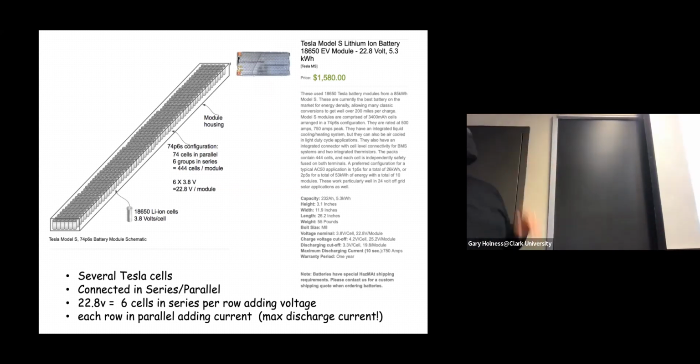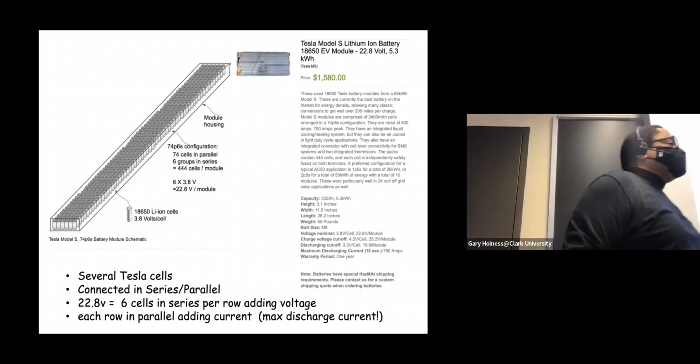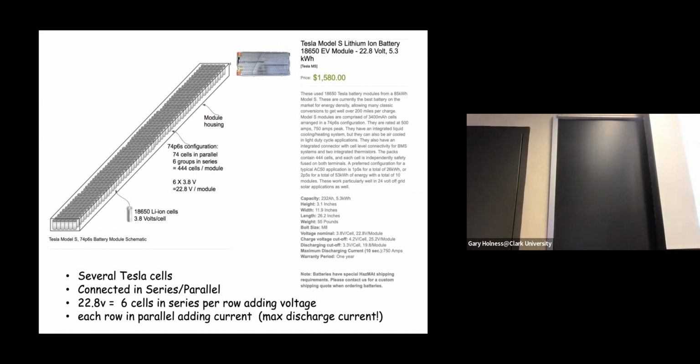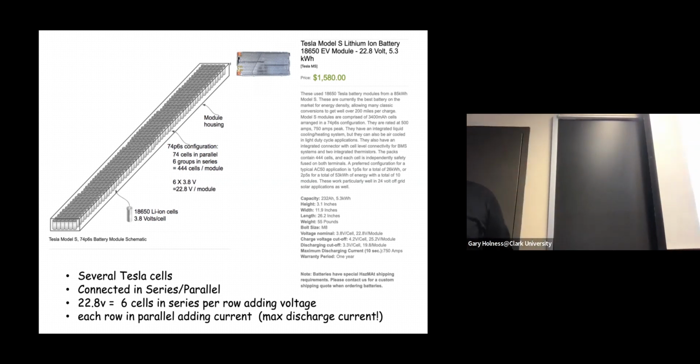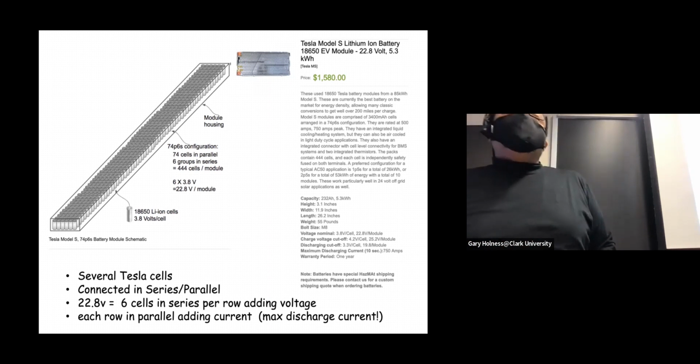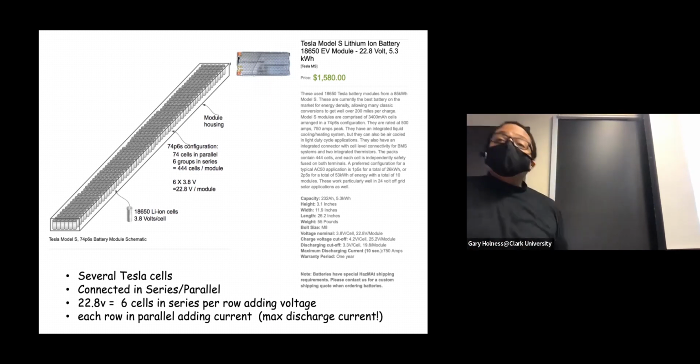And typically, when you deploy a circuit or design something, there's this thing called your power budget. You take all the components you need, how much voltage and current they require, and you add it all up, and you need a battery that's at least that big. Okay? All right. Any questions about it?